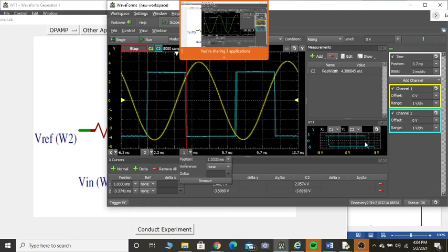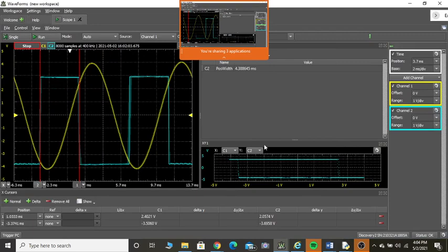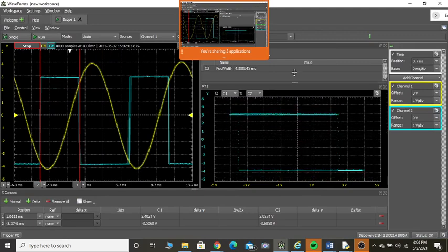So you can measure that here also. This is your VTH value. This is your VTL value. So how do I measure VTH, VTL from this one? If I expand this and make sure that this is going somewhere here. Is this my VTH? This is 1, 2. This is almost 2.5 here. So is it minus 3.5? Is it almost there? 2.4 and minus 3.5. These are the voltages that you can measure here as well as here. Correct?